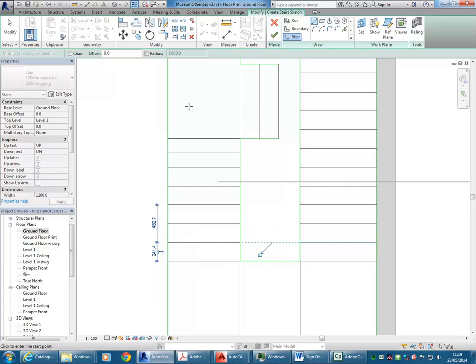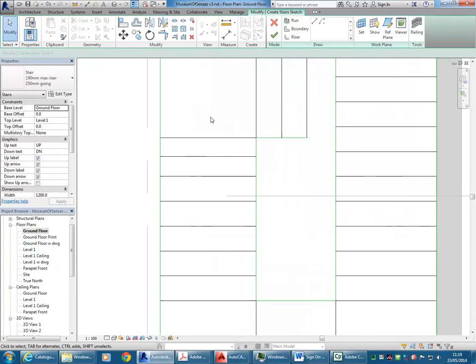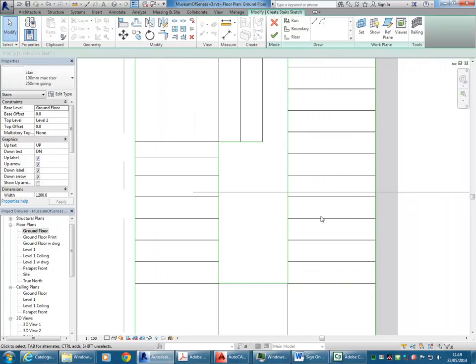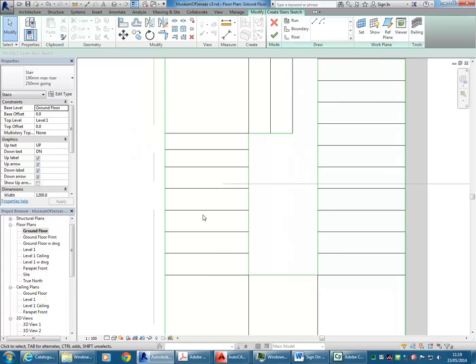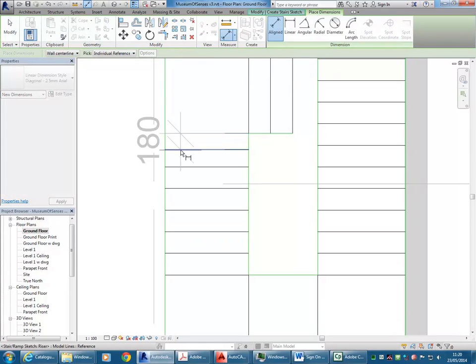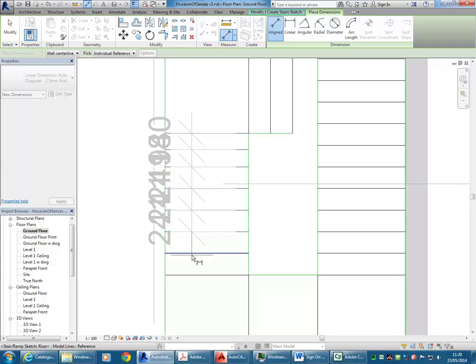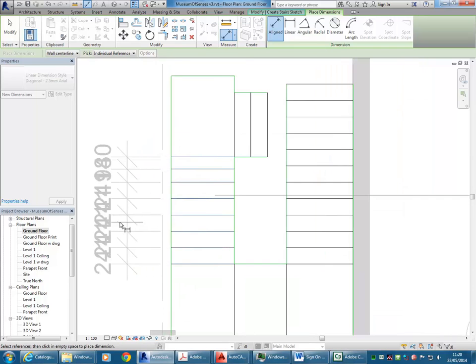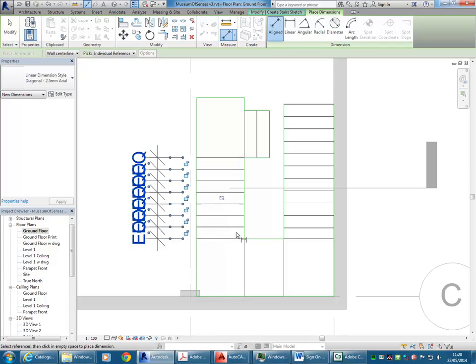This is doing those by lining them up to the other flight, isn't it? You could, but well, no. See, they're different spacings. So these just need to be even within that flight. So how did you know where to put them? Oh, I've just drawn them roughly. So I've drawn the number of lines I need, and now I'm going to use an aligned dimension and dimension all those lines. And then equals will adjust them.